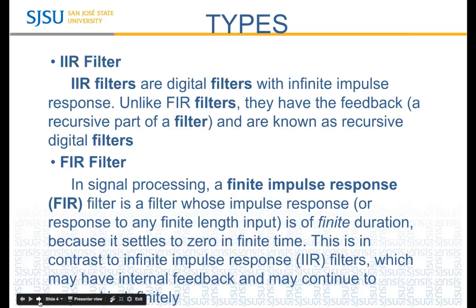IIR filter and FIR filter. IIR filter means infinite impulse response filters. These filters are digital filters with infinite impulse response. Unlike FIR filters, they have the feedback recursive part of the filter and are known as recursive digital filters. Whereas in digital signal processing, a finite impulse response filter is a filter whose impulse response is of finite length.